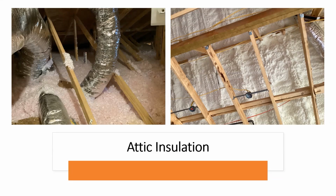If it doesn't, and it's going to fall, then that's not permanently held in place. So it needs to be mechanically held in place, or, as you said, encapsulated with foam. So you're right, that's correct. Just having something there and saying, well, it's inside of a conditioned floor, doesn't mean it's held permanently in contact with its air barrier, which is the rim board.